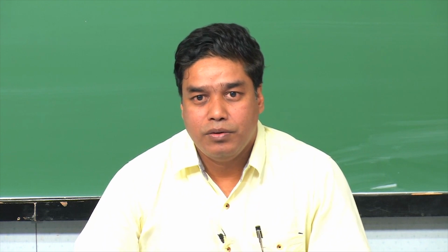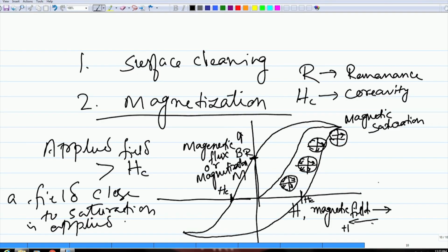So, when doing it practically, you need a reference, or something which would at least indicate, if not tell you the exact value of the magnetic field, that the field being applied is good enough to magnetize that particular part. That is where these field indicators come into the picture.